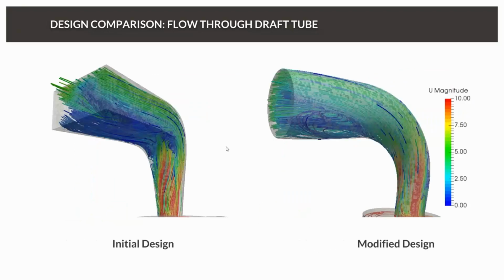And again, we can see here, on the left, there's a lot of recirculation, and the flow is actually pretty messy. Basically, the problem is the angle is too sharp for the speed of the flow. So you can see that most of the flow shoots through and is passing along the top, which is why it is green. And the flow, which is blue at the bottom, is nearly zero, like 0 to 2 maybe. That's basically either going backwards or is chaotic flow, I would say. It's not really exiting in a smooth way, which is what we would prefer.